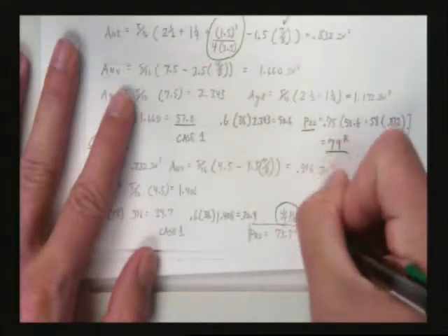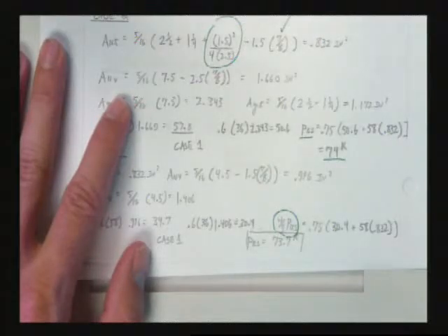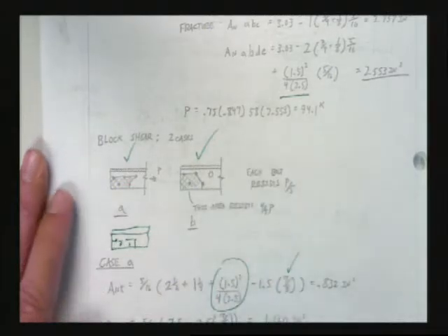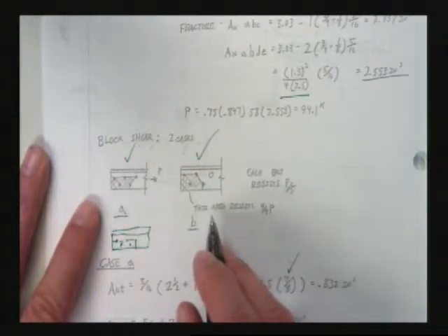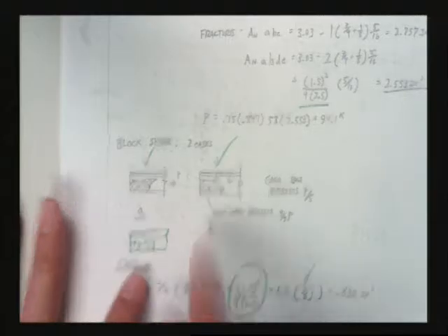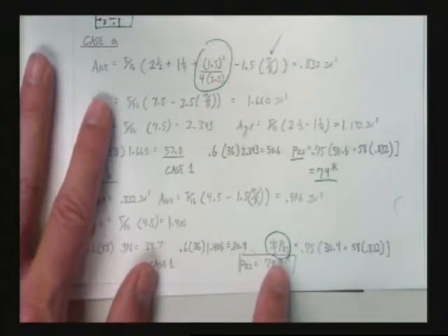We're going to notice when we leave a bolt out that I'm actually going to solve for 4/5 of that load. Why? Because 1/5 of the load is not taken into account because of the bolt not being in the fracture plane. We left the bolt behind, right? And we're assuming there are 5 bolts, each bolt taking P over 5, and that fracture plane only involves 4 bolts. So it only holds 4/5 of the load. You with me? So on the left-hand side of my equation, instead of just solving for P, or phi P, I solve for 4/5 of that.